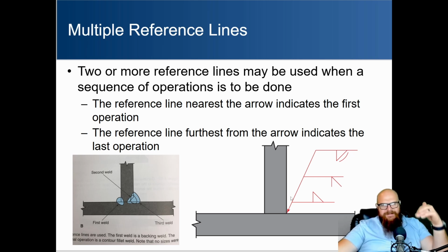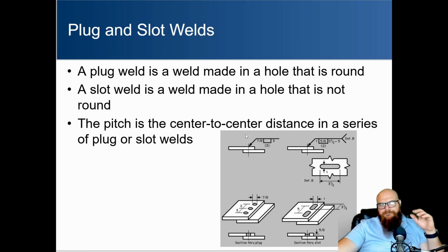So we can use that to tell us what order and how many welds we need to do, which this picture may not be able to tell us. The weld symbol is going to allow us a little bit more information. Again, the two drawings are fairly similar. One's not necessarily more complicated. This one just tells a different story and gives us a little bit more information on the order in which we want to weld these things together.